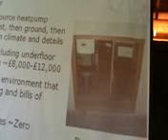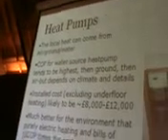Next slide. Yes, so the local heat comes from various different places. On the whole, usually a water source heat pump can be the most efficient, because water stores a lot of energy and it has good thermal conductivity as well. And then ground source is the next most efficient, and then air source least efficient. But it does depend on the climate and the way they're installed as well. And your climate is relatively unusual here, because you've got the Gulf Stream coming in, and you've got relatively mild winters. So an air source heat pump is actually pretty efficient here. And it's usually easier and cheaper to install as well. So it does depend where you are.